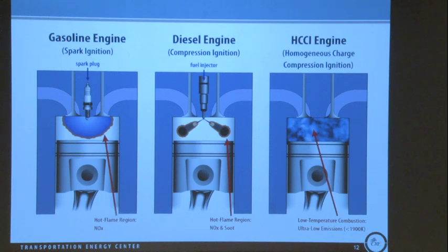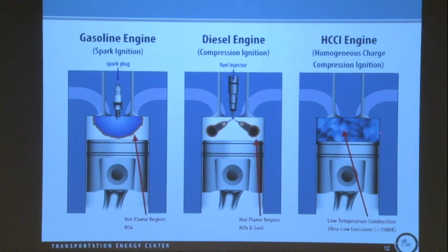And then lastly, there's another concept called HCCI, homogeneous charge compression ignition, whereby temperatures are low enough and the mixture is dilute enough that you volumetrically auto-ignite as opposed to forming any sort of flame like you would in the other two forms. And the issue here is, if you truly volumetrically ignited the whole charge, you would have such a high pressure rise rate that your engine would ping and knock as you drive. So you want to avoid that.